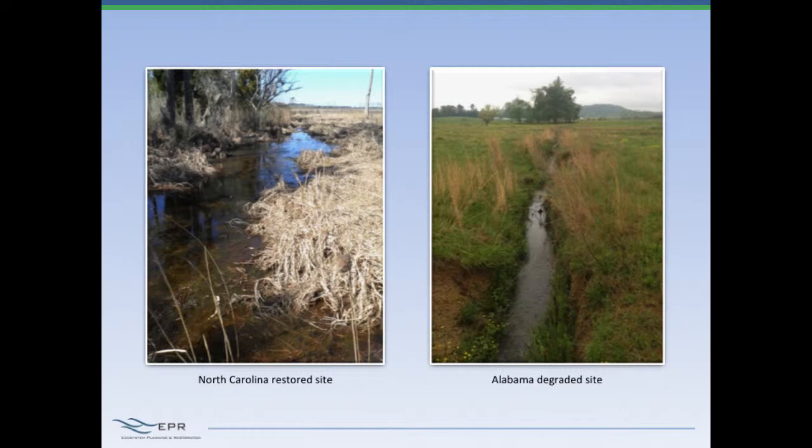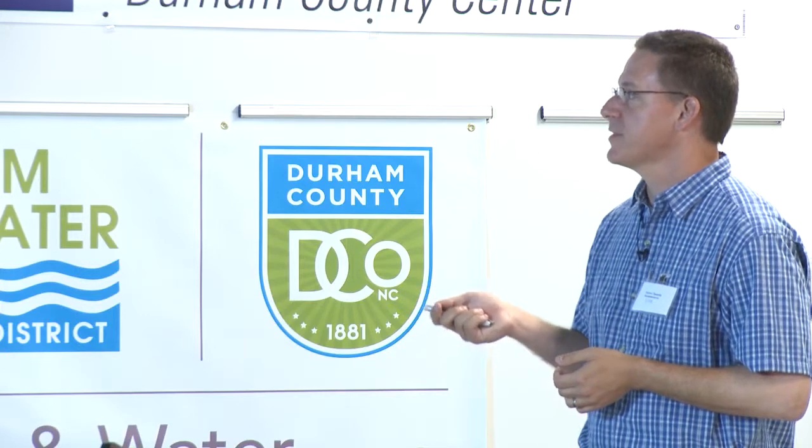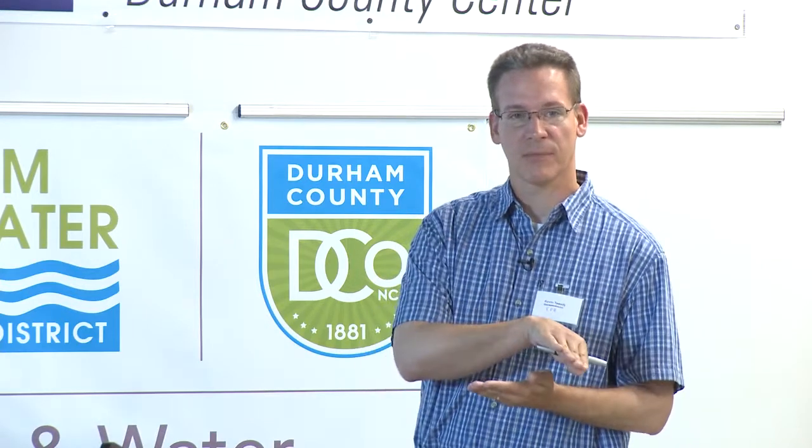As you start to increase drainage area and increase slope, you get more and more channel definition and channel morphology developing. So what we've done is use this as a guide on several fairly large-scale restoration projects in the coastal plain, using this tool to help guide us in, okay, this is an appropriate spot to do more like headwater wetlands, braided design. Coming on down the valley, maybe things steepen up a little bit. Sometimes you've got escarpments where the valley slope steepens. Those would be areas where you typically find more single thread.